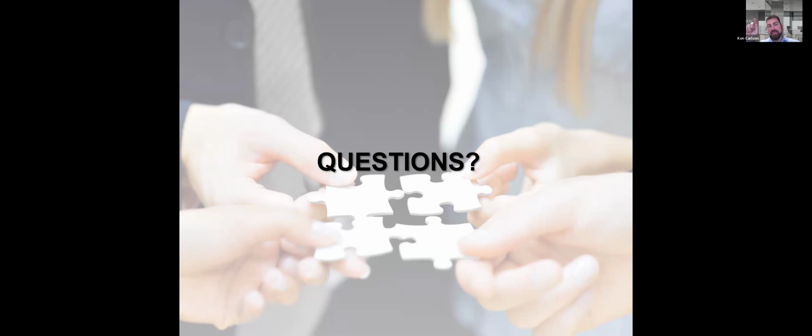It'll run the math in the background. The example that we did is just real basic, straightforward. It doesn't take into account heat gain. The programs, and even the Manual J if you did it the manual way, it's an advanced Excel spreadsheet. You put in all the inputs, you would put in what the north facing wall is, and it would add a solar load to that north facing wall.